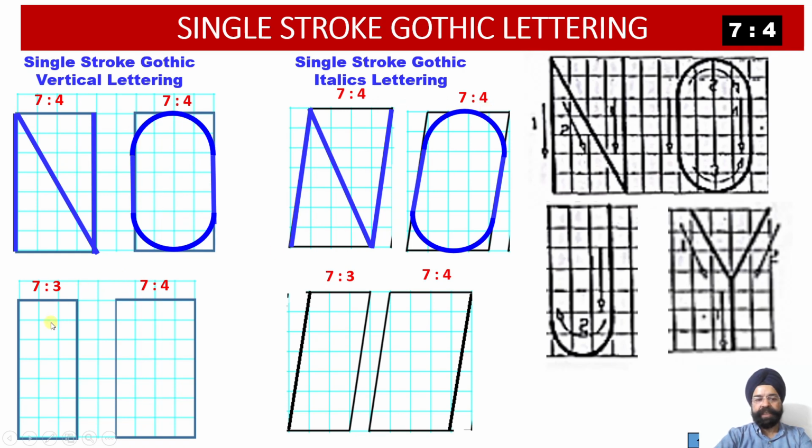Now we are going to pick up the third exception which is there in the form of J. I told you that J is there in 7:3. You can see I put down the ratio 7:3. So if we have to write down J, it will be possible in 3 strokes. You can check, there is a semicircle for 3 blocks. So 1.5 is my radius approximately. Just see over here, 1.5 curve I am going to draw, and then a vertical 5.5 blocks line I am going to draw. In 2 strokes I will be completing J.